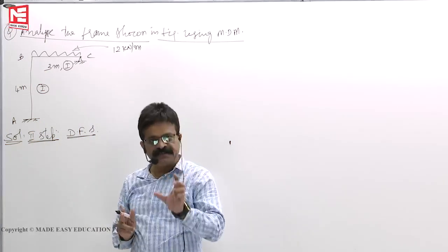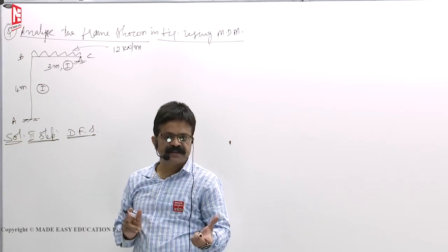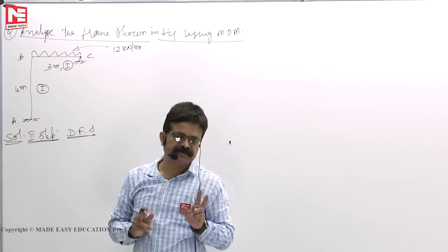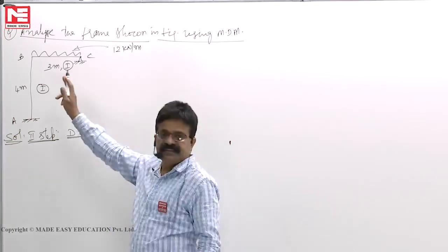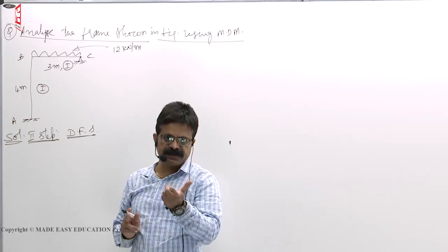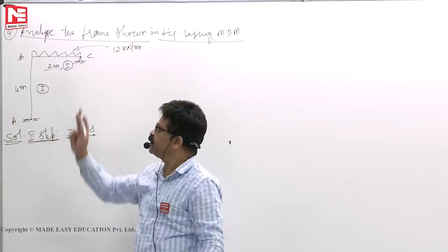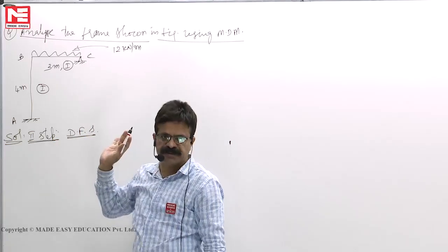At the fixed support condition, one member has infinite stiffness, so that it will not permit the members to rotate. A rigid joint will take the moments, and it will rotate the members also. Other than that rotation, there is no difference between rigid joint and fixed support.